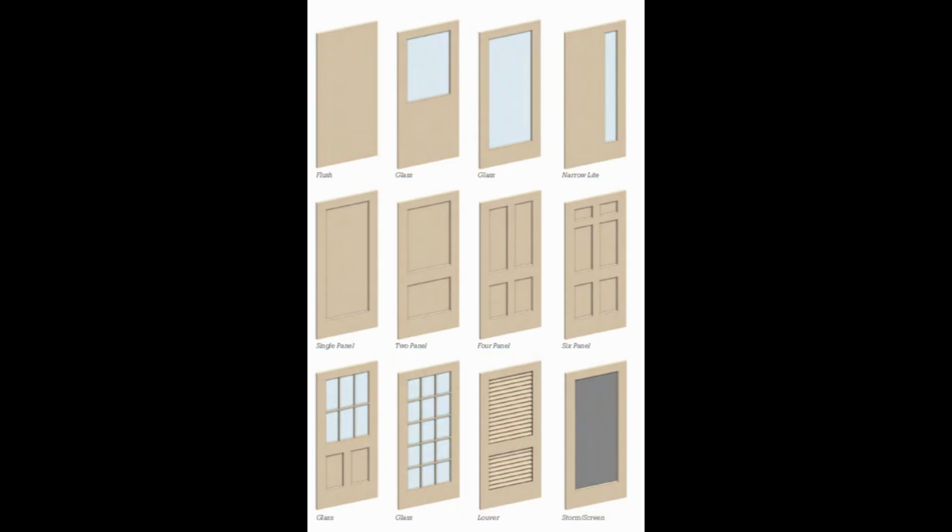They also talk about wood doors. At one time, all doors were made of wood. For simple buildings, primitive doors were made of vertical planks or Z-bracing, which were the common ones. For finished buildings, there were stile and rail doors that gave a sophisticated appearance. Stile and rail doors can be made of solid wood or composite materials with veneer faces and edges, and we're also going to show a picture right here.